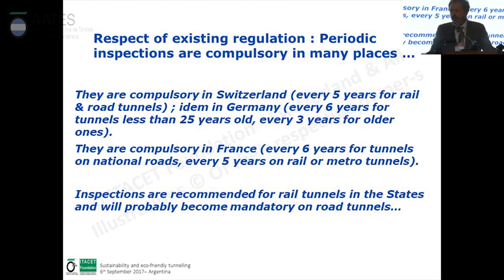If we look through the existing regulation, periodic inspections of the structures are compulsory in many places. They are compulsory in Switzerland every 5 years for rail and road tunnels. In Germany, every 6 years for young tunnels, and every 3 years for older tunnels.